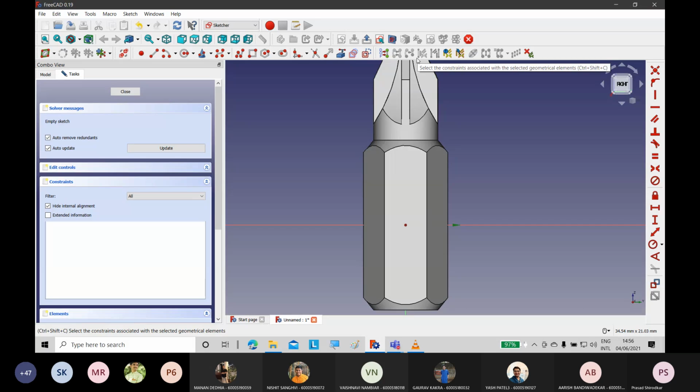We are going to do that by cutting a triangle. So import constraint and select this vertical line so that you can get some reference, and select this polyline option and do the section and just construct a small triangle.